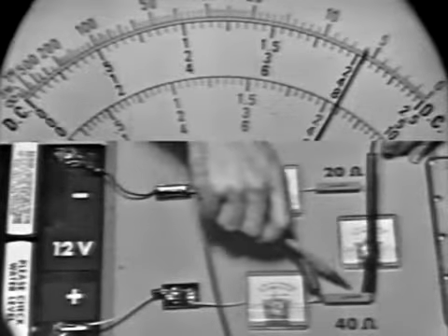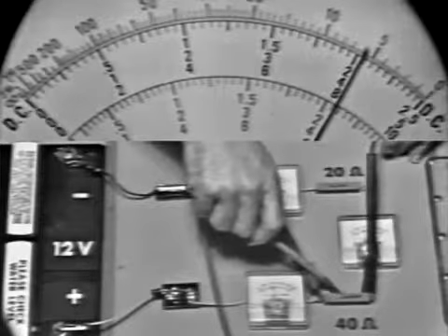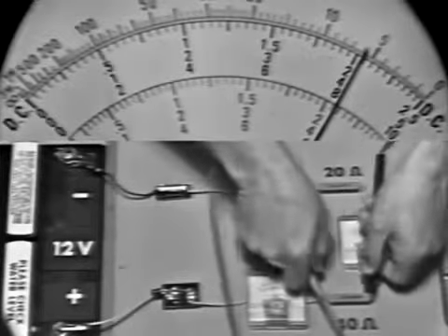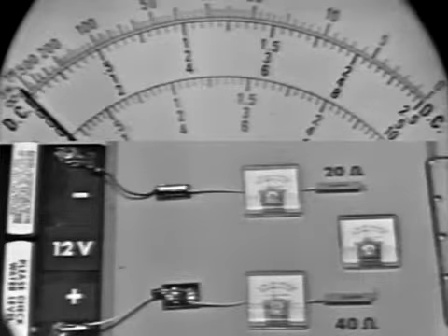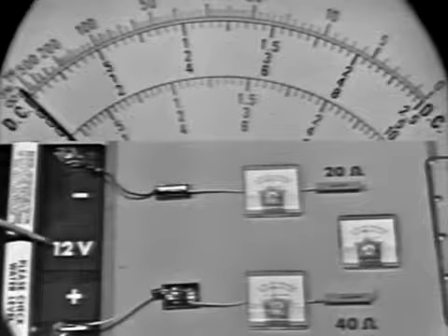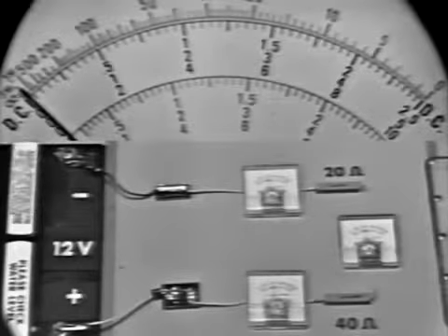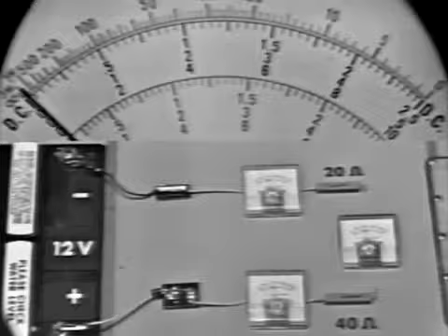Okay, here we get about, let's call it 8.2, the bottom numbers on the DC scale. Okay, we have 4.3 volts here and about 8.2 volts here. If we add these two voltage drops, their sum is equal to about 12.5 volts, or somewhere near the applied voltage. And of course, this satisfies Kirchhoff's voltage law.